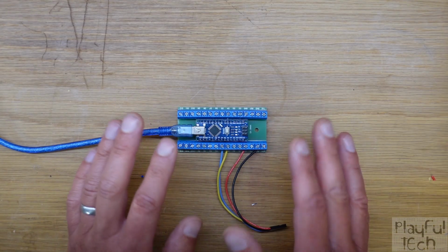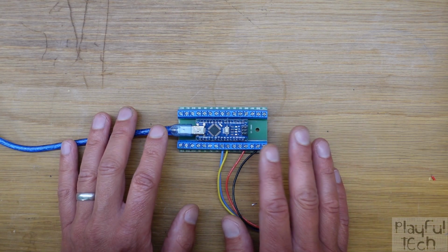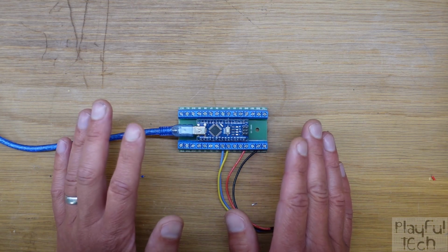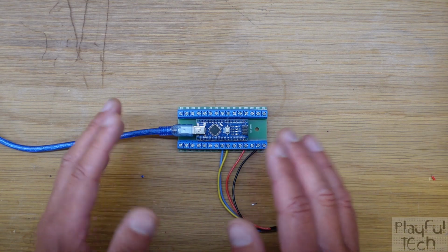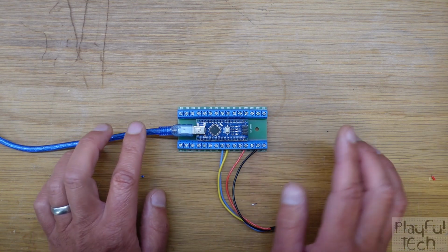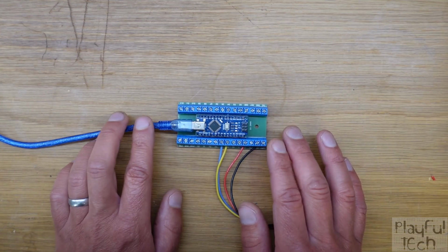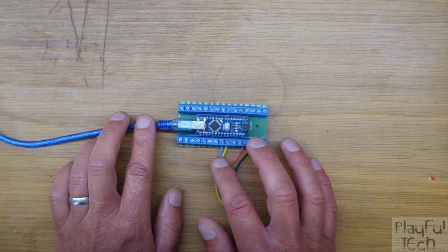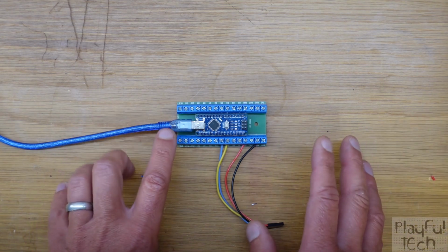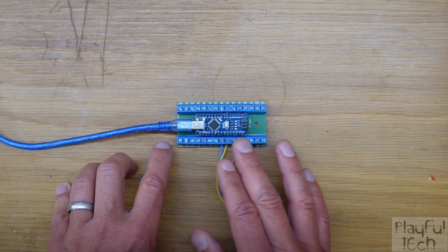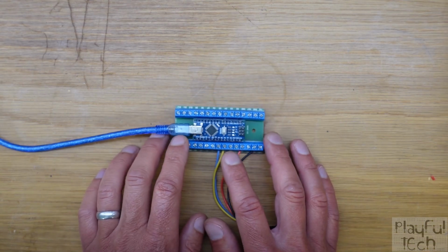Now, I'm not going to go into too much detail about I2C here, that will be the subject of another video, but the thing to know is that I2C is a bus interface. So rather than use a GPIO pin to send or receive high or low signals to a single device, it can send and receive data to many devices, all connected to the same shared clock and data pins. Every device on the bus has a unique address, and the Arduino is able to route data to a particular device by including that address as part of the data packet it sends.